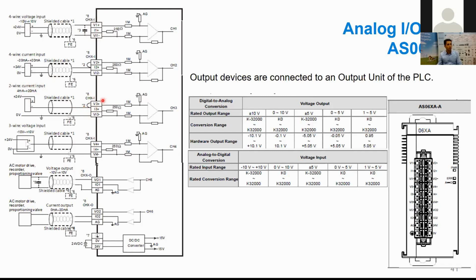to make short circuits. And on the other hand, some modules, this is one of the examples, need additional 24 volt DC. You see here. So you supply the CPU, that's fine, but not enough for this module. You also need to supply 24 volt for this module. Okay.